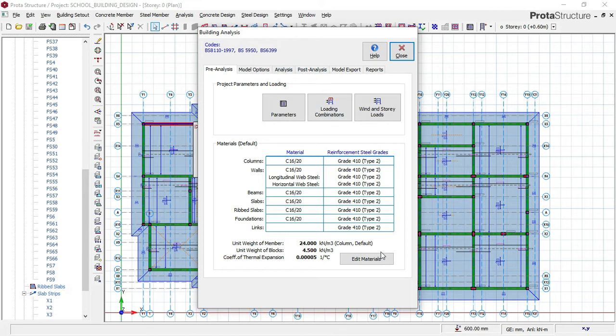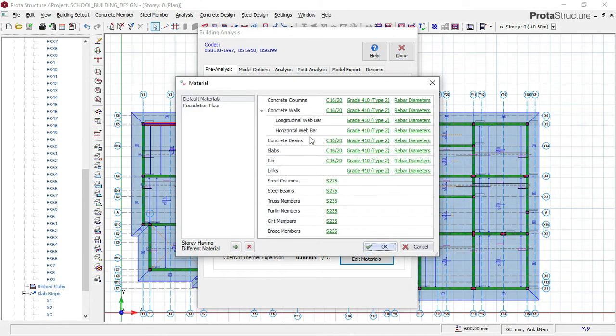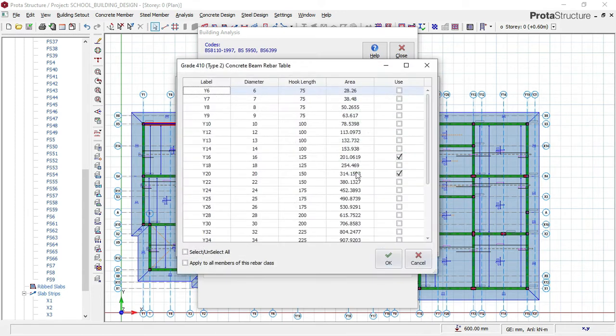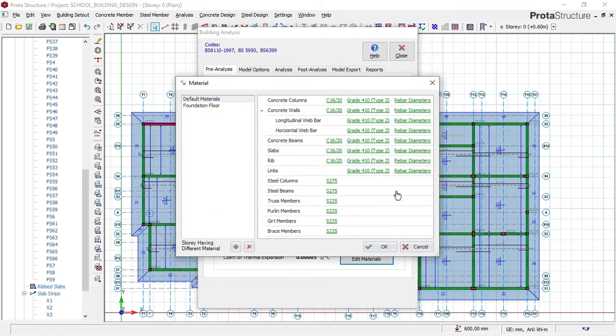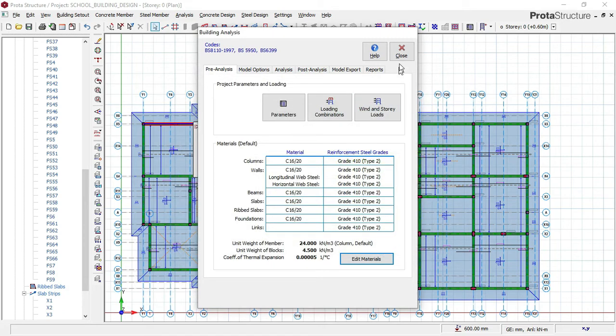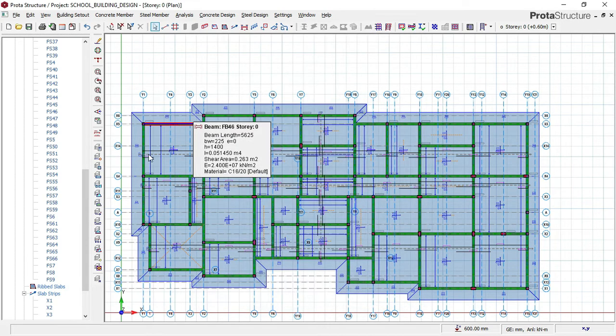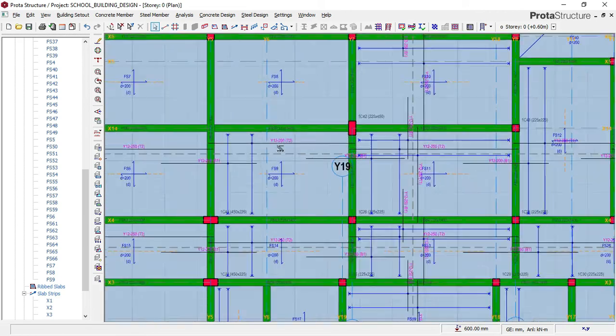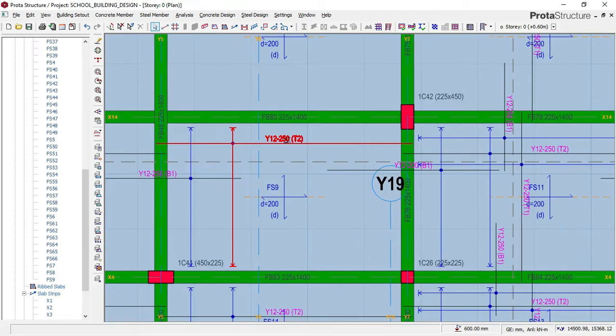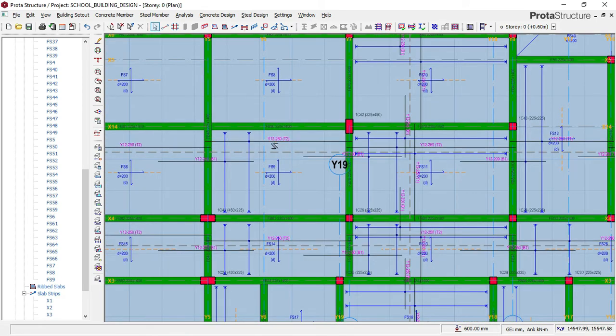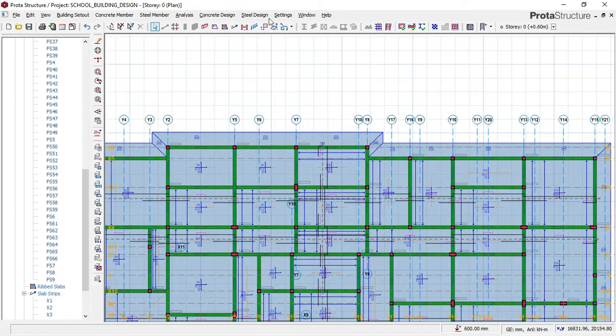Okay, so right now I'll go here and say edit, and then check my beams, my beam reinforcement, and then assign. Okay, I want to use minimum 16 and maximum 20. That's fine. I'll say okay, and then say okay here, and then say close. That's fine. So right now, once you're done updating your steel bars after designing your slab, you can now go and check here.